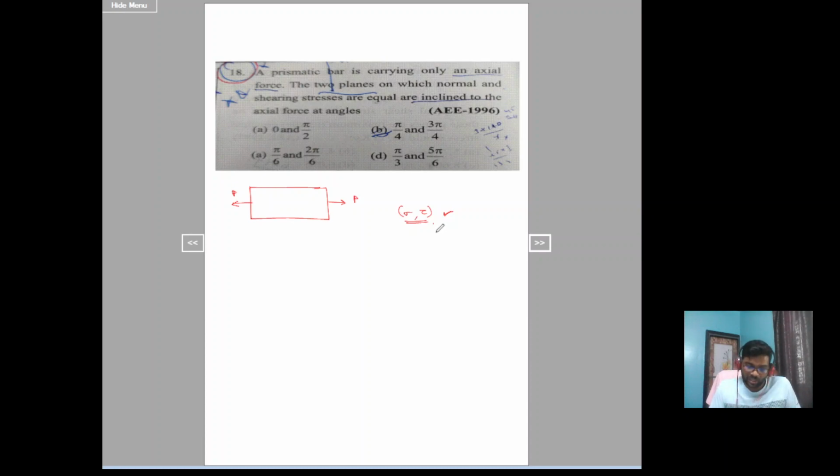So in case of uniaxial stress condition, this will be one of the principal planes. If you calculate tau max, it is equal to the radius of Mohr circle. Let's take this as sigma, directly as stress sigma, that is sigma minus 0 by 2, which is equal to sigma by 2. Now let's calculate sigma average.